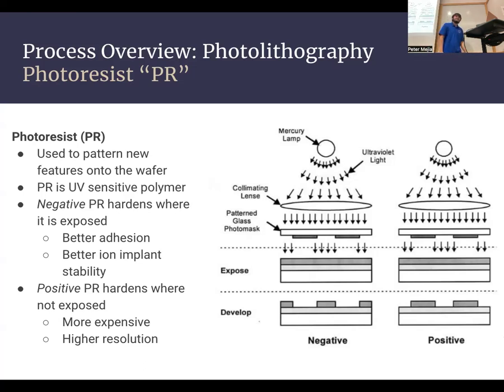What if I use negative photoresist? Is there something specific? Well, I think it depends on your mask too, right? So if you have a certain mask where you do want it to expose, you would use negative, and otherwise you'd flip the opposite.